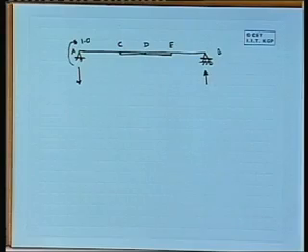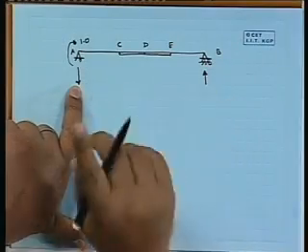So, this will be one force and the opposite force, and they will give a couple, and the value of that couple should be equal to the applied couple, the applied moment. These two forces will act in a reverse manner. So, this is clockwise, it will be anti-clockwise. This side reaction will be this side, this will be that side, and they will produce a moment of 1.